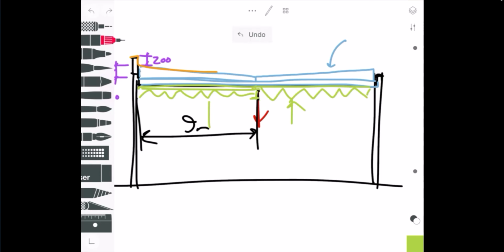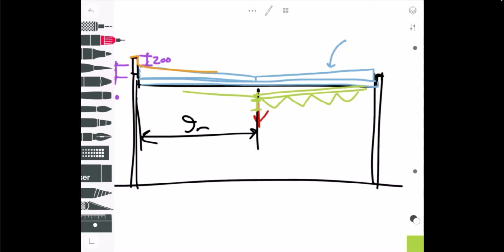Because by sloping that stuff, and I'll just draw it drastically here so it's easy to see, there's the beam, and here's now that joist. By taking that approach, there's no cost really. Maybe there's even a savings because you've just used less steel.